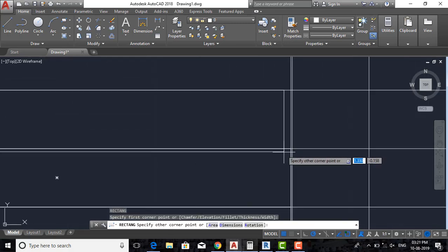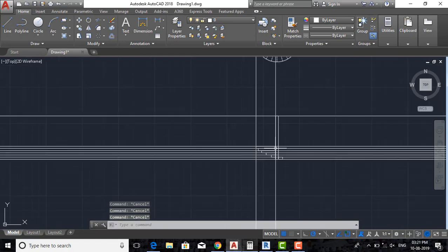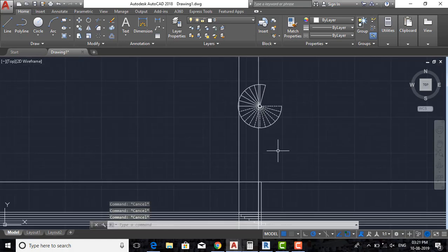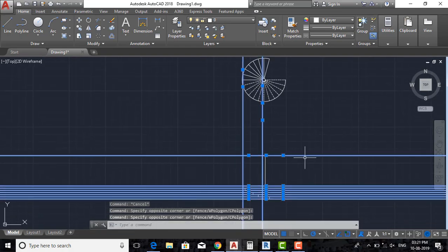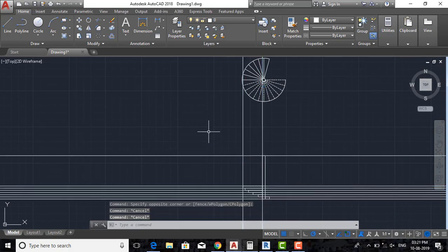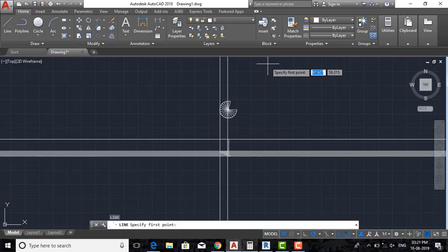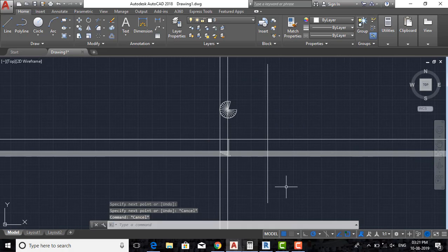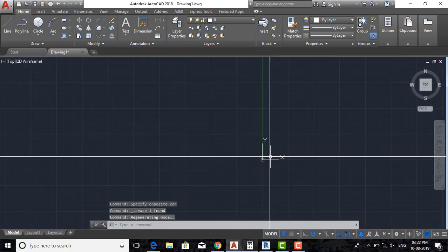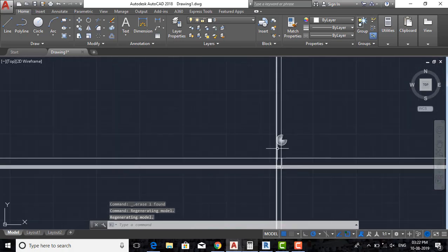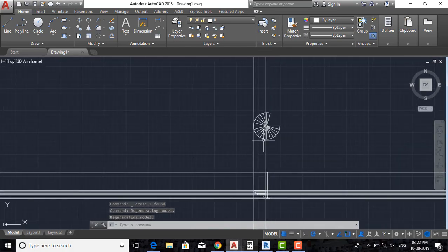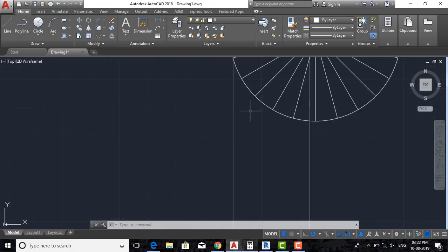If you want to work in AutoCAD, you should know how to draw all the details with the help of these projection lines. These lines are very important, because if you draw a single line, its length will be up to a certain limit, but the X line length goes up to infinity. You can't find the end of these lines.